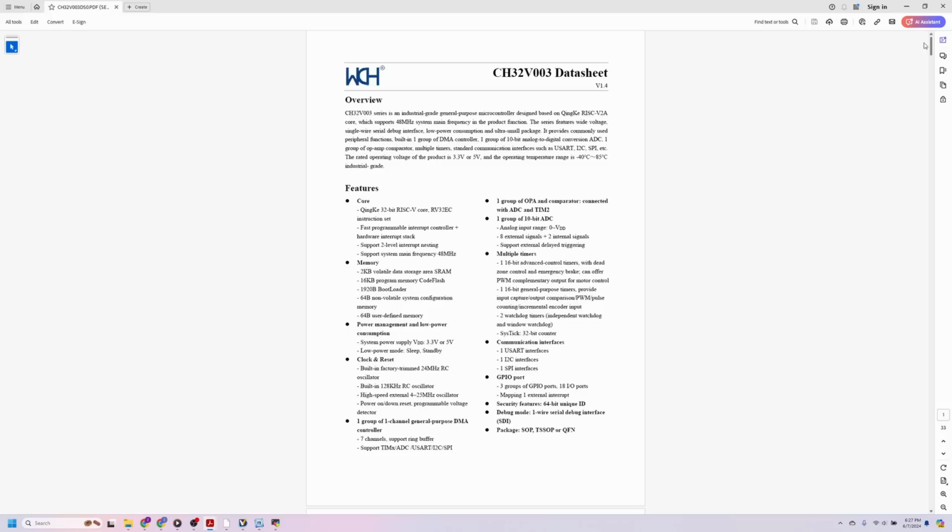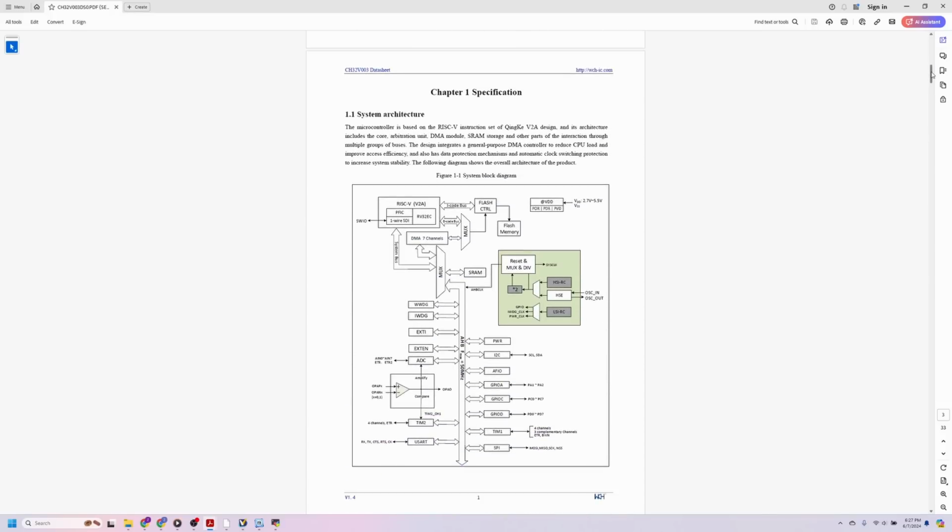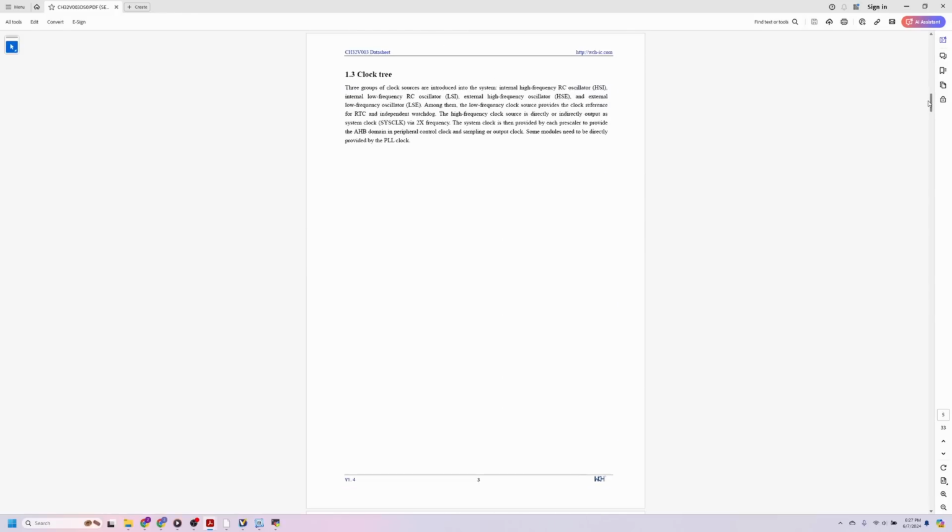My complaints are in regards to the documentation. The datasheet, the reference manual, there's a core manual, and a bunch of other how-to guides. They're really well written, and they're written in English, unlike what you get for the PY32. But I could not find any documentation for the hardware drivers, despite the fact that they're used by default in MounRiver. Now, to be fair, Puya also does not have documentation for the drivers on the PY32, but those drivers are basically just copied from STM32s, so ST's 2000-ish page HAL manual is directly applicable.